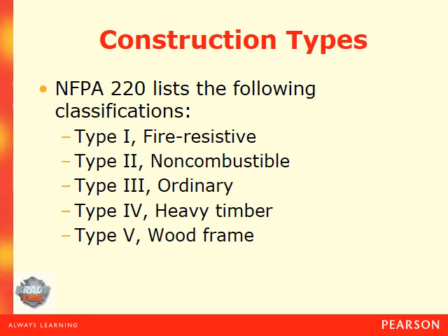Type 1, and we'll go through each of these, is your fire resistant type structures, stuff that's made up of things that won't burn. So you're looking at concrete, reinforced steel, steel girders with fire insulation around them. And then your type 2 is non-combustible, and it's very similar to your type 1, except the structural members aren't protected from fire. So that would be like your warehouses. Your type 1s could be hospitals or parking decks.